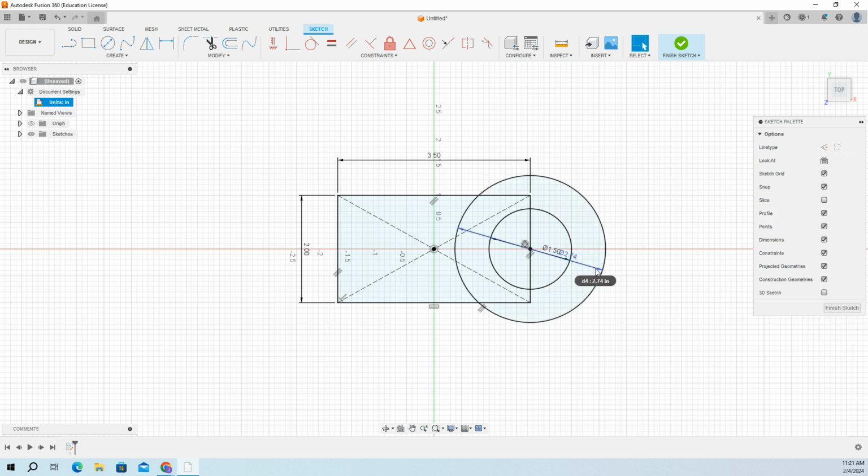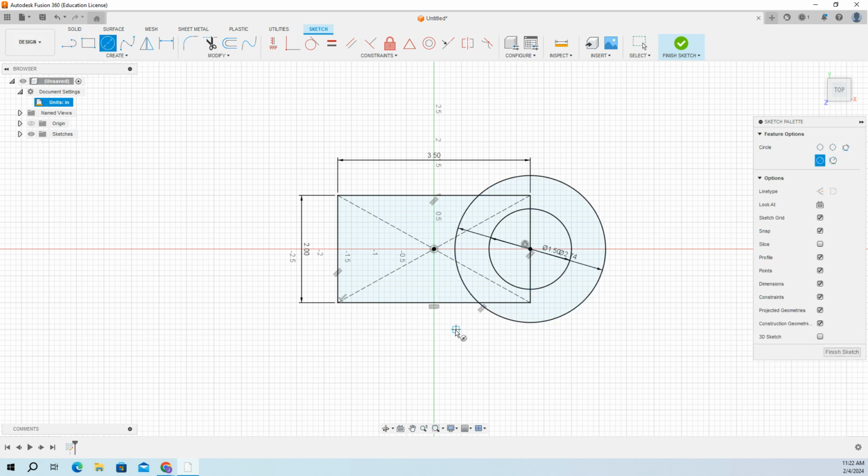All right. So we have this hard edge right here. I'm not gonna do the edge yet. We know the way to do it, the old way that we've already done. You go tan radius, right? So I could go circle, right? They want the radius to be 0.37, so that means the diameter is 0.74. So I could go 0.74.